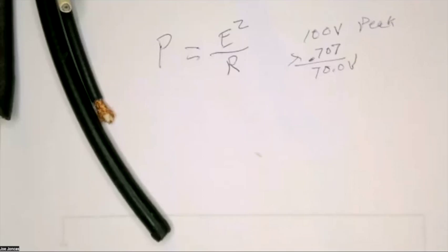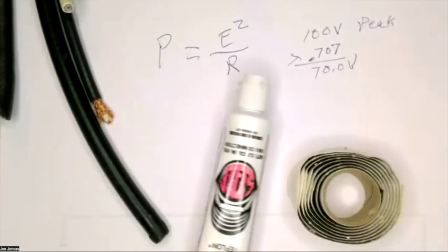That is true. And one of the ways is you want to make sure that after you've made a connection outside, that you have made it waterproof. You can use shrink tubing or you can use self-amalgamating tape to put over the connection, which will help keep water out. We also have, actually, here's a little of each.